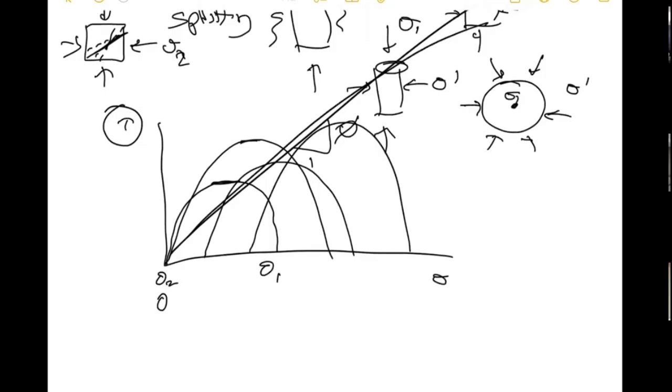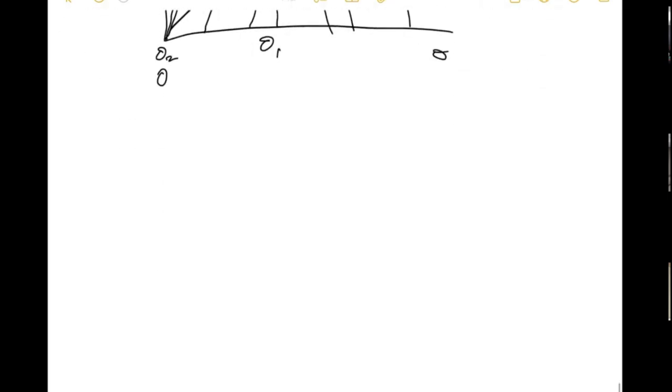The idea being, if your shear stress is outside of this envelope, it's failed. And if you're inside, it's okay. And notice, if it's confined, it's got a higher strength than if it's unconfined. Okay. Is everybody with me? Yep. Yes. So this is as far as we're going to go in terms of strength discussion.